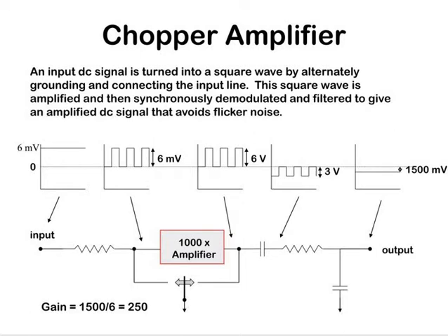If the output voltage is high compared to the input, then that is called a step up chopper. When the output voltage is low compared to the input, then that is called a step down chopper. And the other use of the chopper is to avoid noises. Very important point is noises.